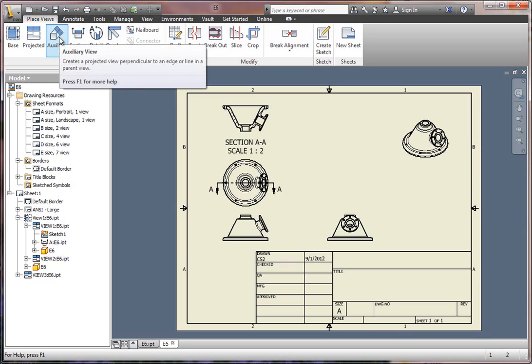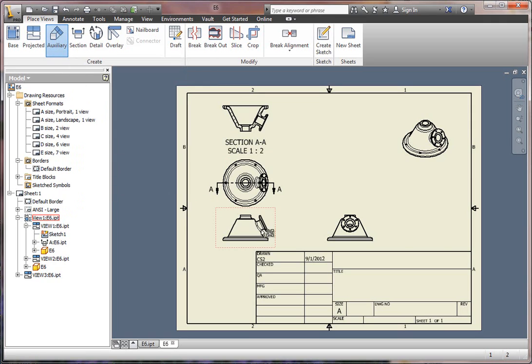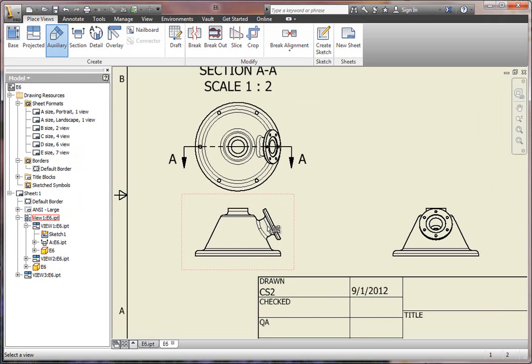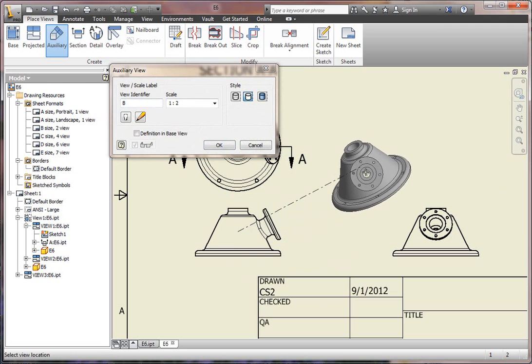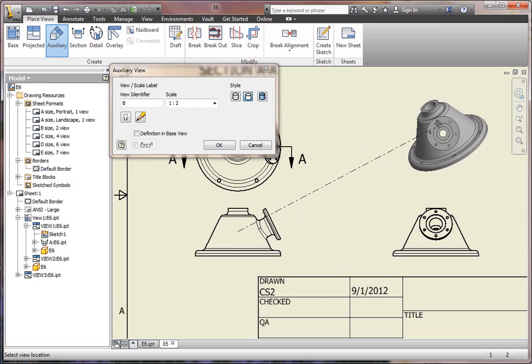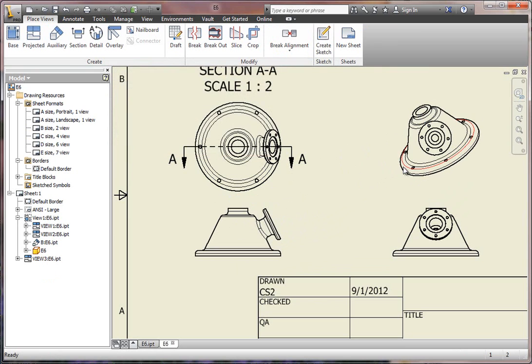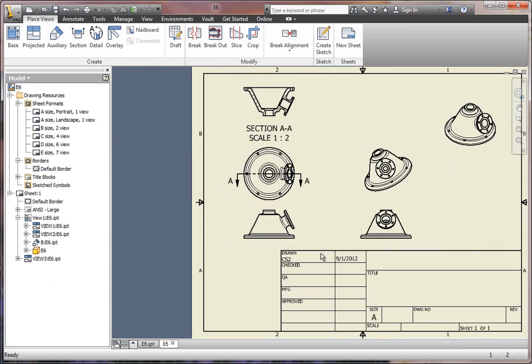Now for the auxiliary view, find that. Go ahead and select auxiliary view, and maybe zoom up a little bit to this view, but give yourself some space over here, because an auxiliary view basically unfolds off of a selected edge of the model. Once you have auxiliary view selected and you are zoomed up, go ahead and select this edge on the right hand side of that flange. Click on it again, so it's basically 2 clicks, and then drag it off in alignment wherever you'd like to position it. Like I'm going to put it right there by clicking. Okay, so there's an auxiliary view.